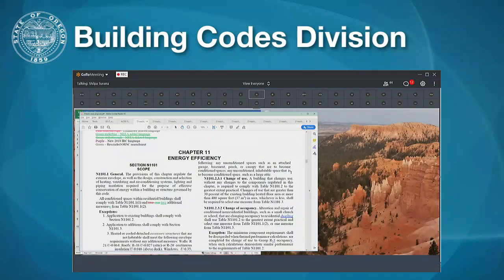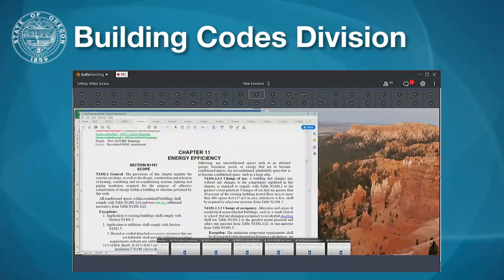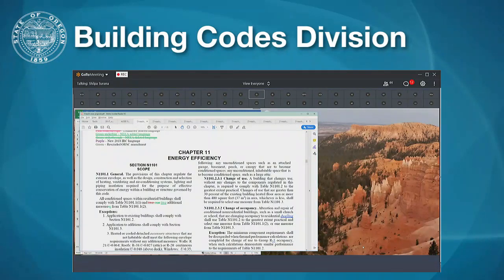In overview, the major changes which we support are bringing in performance testing to achieve air sealing and duct performance. Our proposal introduces prescriptive requirements to achieve an air leakage test of 4 ACH50, and limits the prescriptive duct leakage test to 4 CFM per 100 square feet for the ducts.